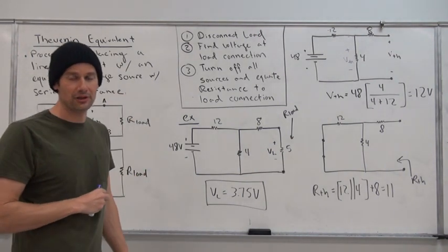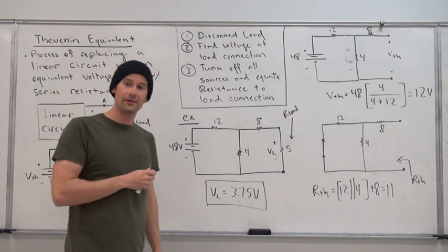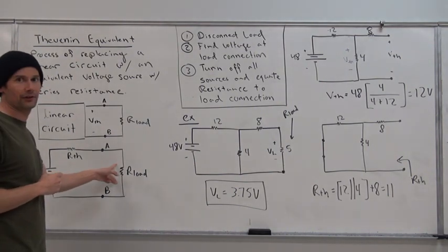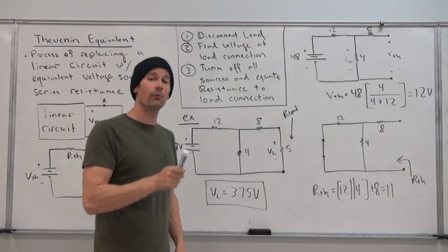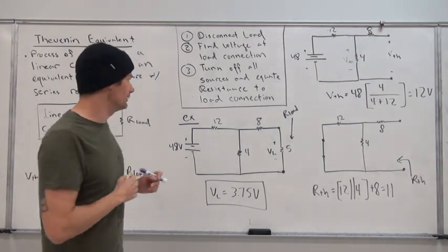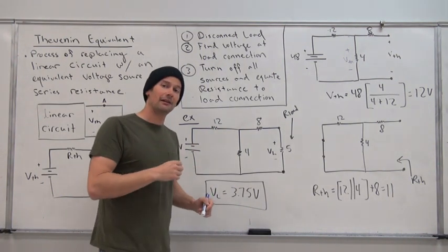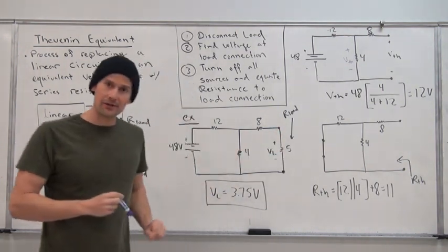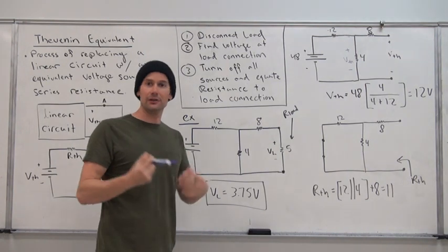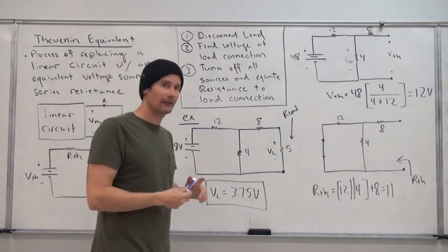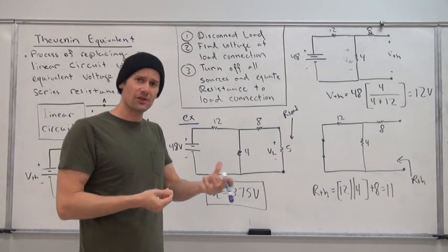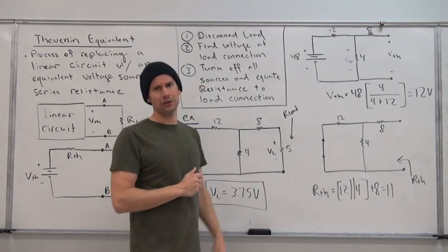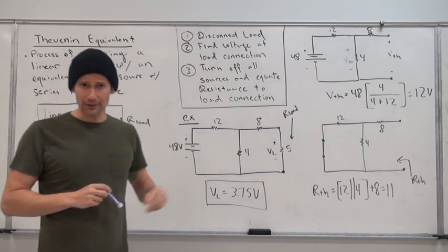So you guys should go through, punch it in on your calculator, and make sure that that is consistent. Sure enough, 12 volts in series with 11 and in series with 5 does give a voltage across that load that's the same. And that is the absolute point of the Thevenin equivalent: we replace an entire network with one that provides the same exact delivery of voltage to that load itself. From here, we have a very nice design technique that allows us to solve a complex network just once, so that we can continually work through and determine the appropriate value of the load that we want to connect up to this element.